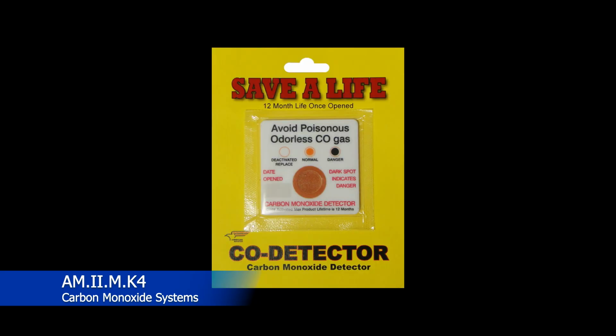All right, and then here's your most common carbon monoxide detector. These things are like $1, and you change them out on airplanes every time you do an annual on it. As carbon monoxide gets exposed to that little orange circle in the middle, you'll start to see it turn black, and as it turns black, you'll know that carbon monoxide is in there. You can have other types of carbon monoxide detectors on aircraft, especially the more sophisticated they get. However, the vast majority of aircraft out there are small GA planes, and this is going to be the most common carbon monoxide detector that you're probably going to come across.